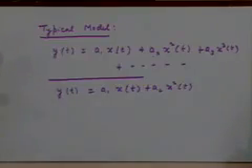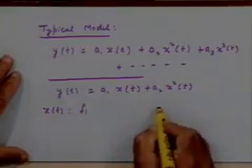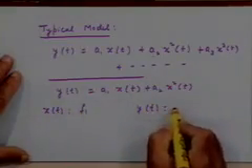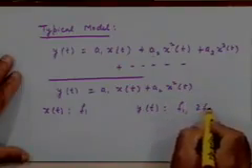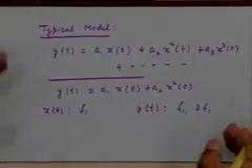So cosine square you can write as 1 plus cosine 4 pi f1 t, right? So now what are the components present in y of t? We have f1 and 2f1. 2f1 was not present. The input was containing only f1, right? So the input signal contains a frequency component f1, output contains f1 as well as 2f1. This is a very simple situation.